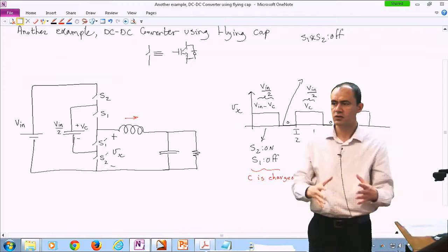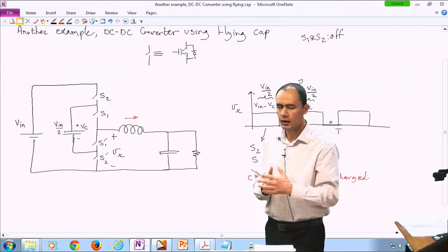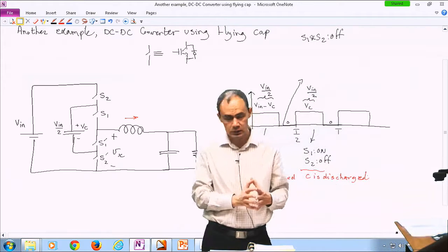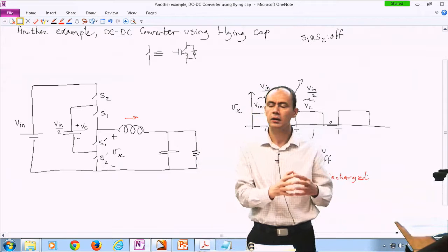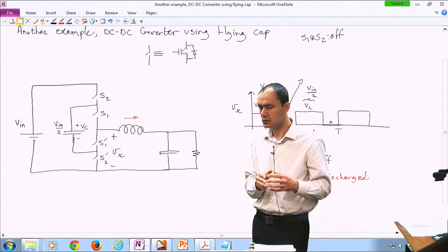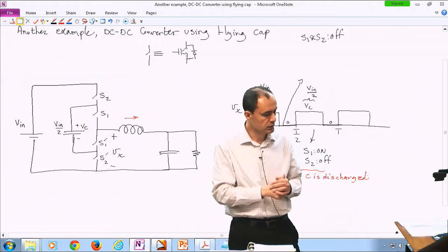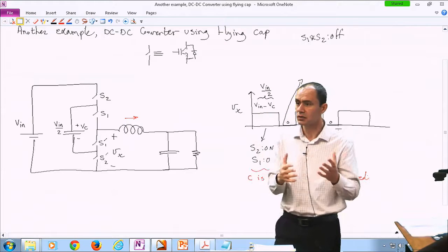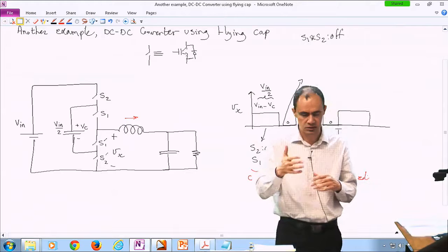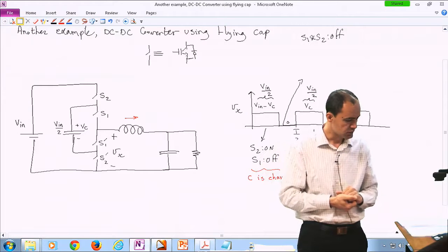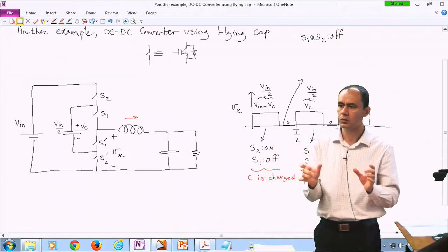So one observation is we don't need a bidirectional current to be able to regulate the voltage of this capacitor, or even a positive current would do it. So technically all we've got to do is, if our inductor current is symmetric, and it is actually symmetric unless there's a transient going on, just make sure the length of these two modes are almost the same.